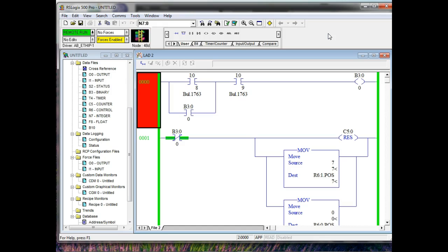You know, those are backwards. When we send it from the computer to the PLC, we call that download, because the PLC is considered the boss. If we're bringing it from the PLC into our computer, we call that upload. So that's backwards from what you're used to on the internet, right? You understand that?